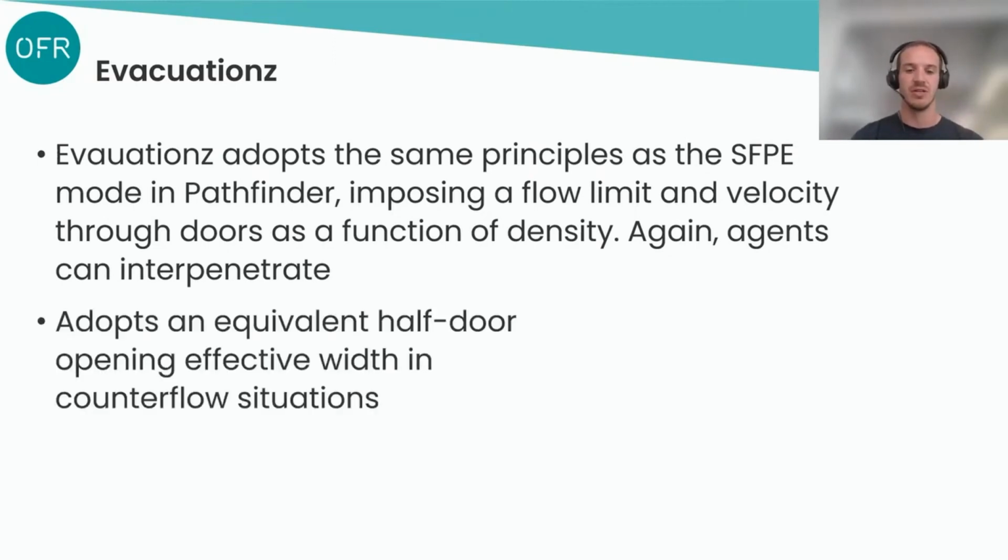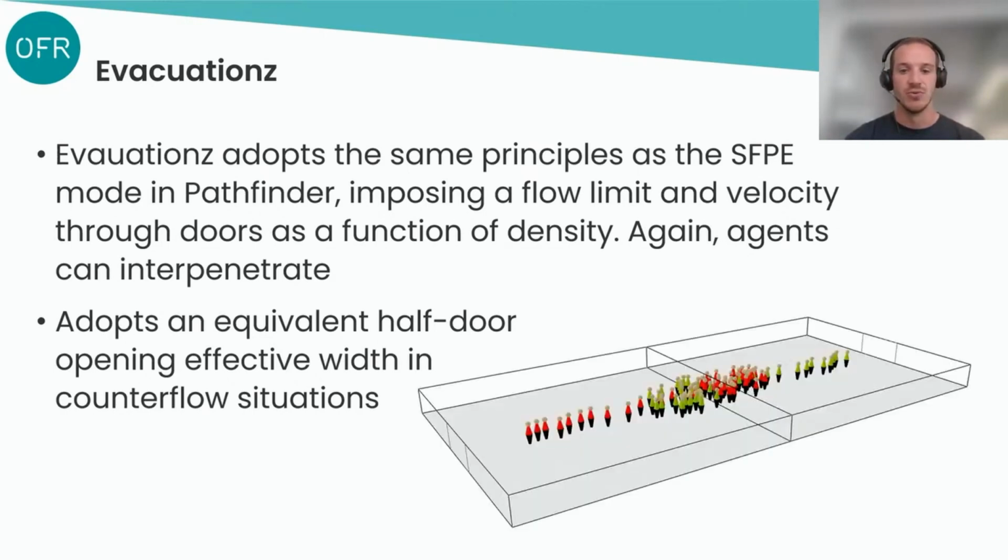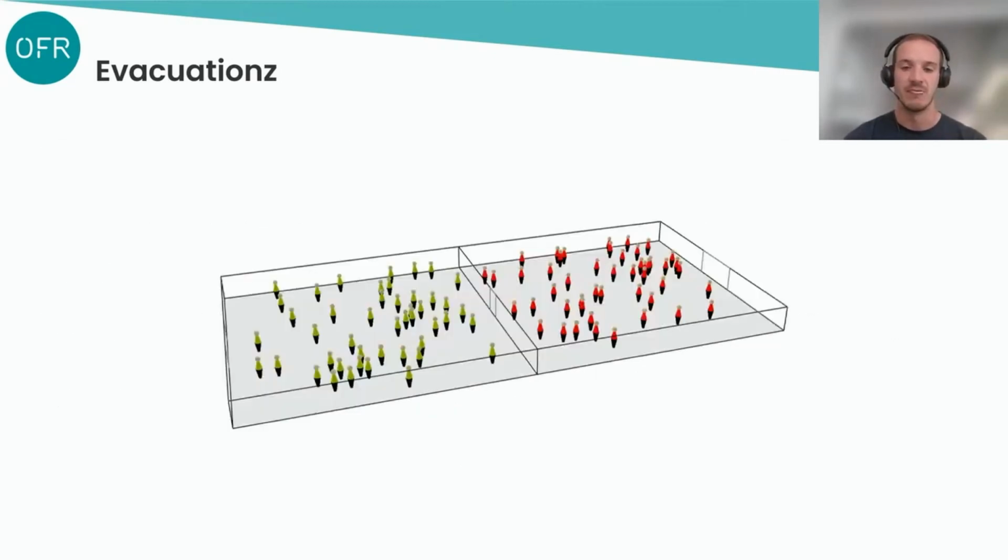For this work, the model has been updated to capture counterflow, whereby an equivalent half-door opening effective width is adopted as the first pass to compare the results of this simulation tool with the trials. Evacuations outputs into smoke view, so you can view the movement as you can with Pathfinder.